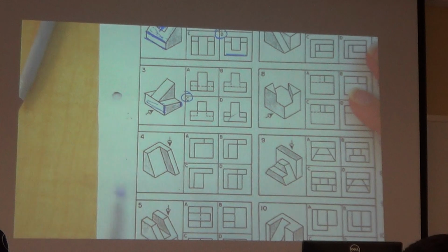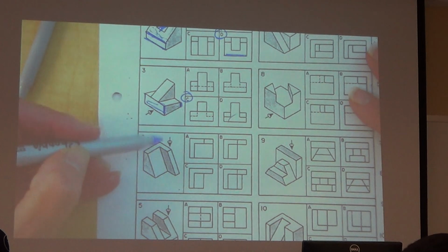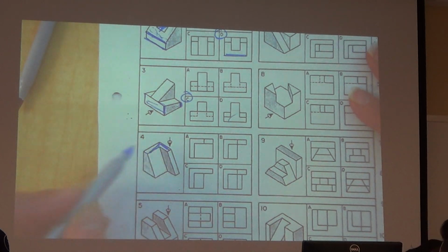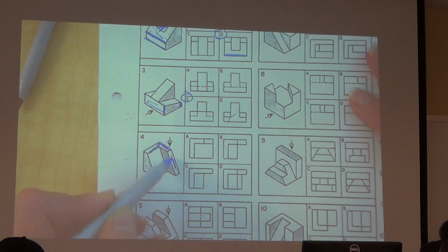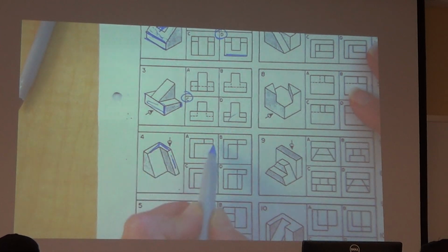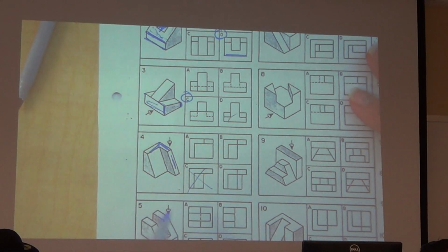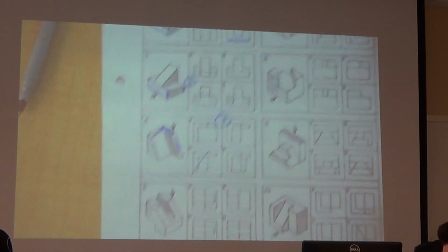Okay, number 4. So we're looking at a three-dimensional object again. We're looking down, we're looking at the top. So I see this backwards L. So each one of these has to have an L. But notice this protrudes out. So again, this surface, even though it's inclined, it's actually sticking out and it looks like a vertical. So I'm going to have an L. I'm going to have a little piece here. So I know this one's wrong. And then this, again, even though it's slanted, it looks like it's just horizontal. Gustavo? Was it B? Yes. Okay, let's look at the next one.